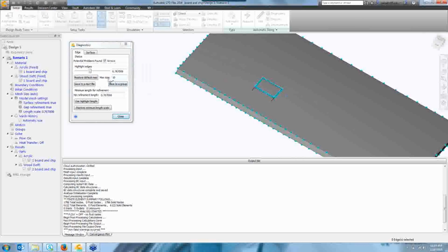It'll just make sure that there's enough mesh to capture all of the surfaces. So we go from first having all of our edges, then we grow into building our surfaces, and then, you know, we could have some kind of meshing error if a surface is missing or can't be meshed, has some sort of intersecting surface, something like that. Then we'll go into volume meshing.